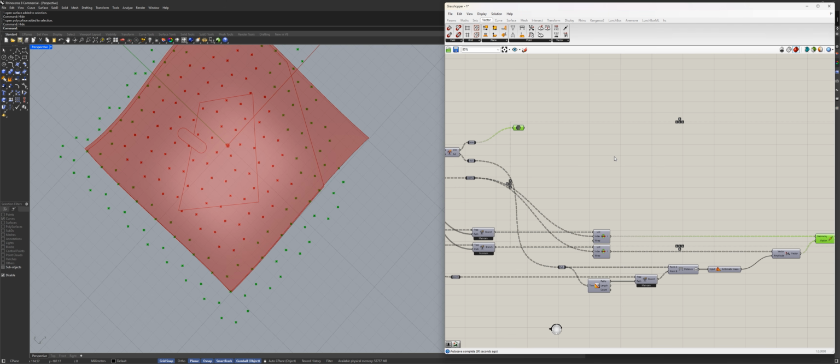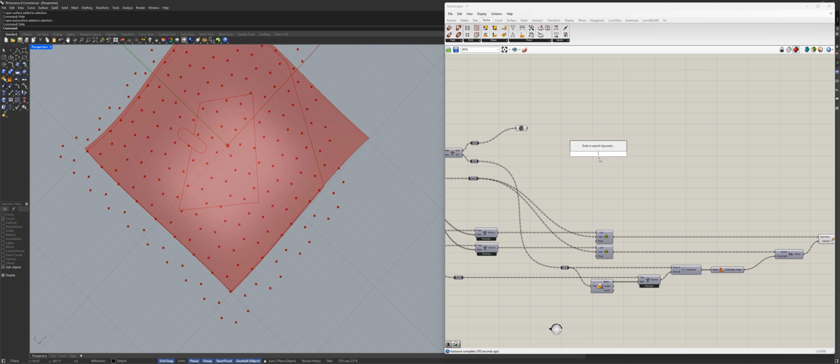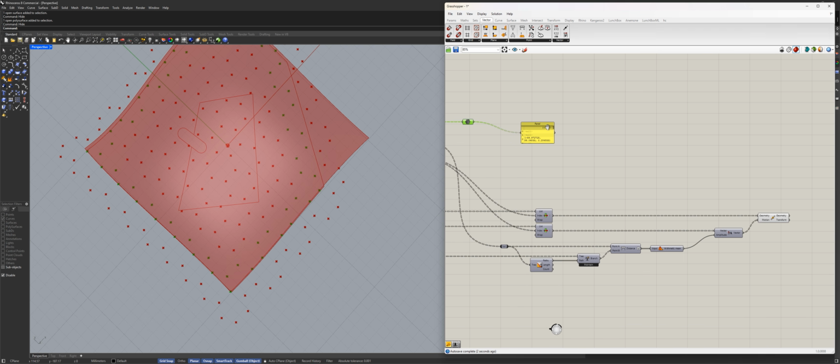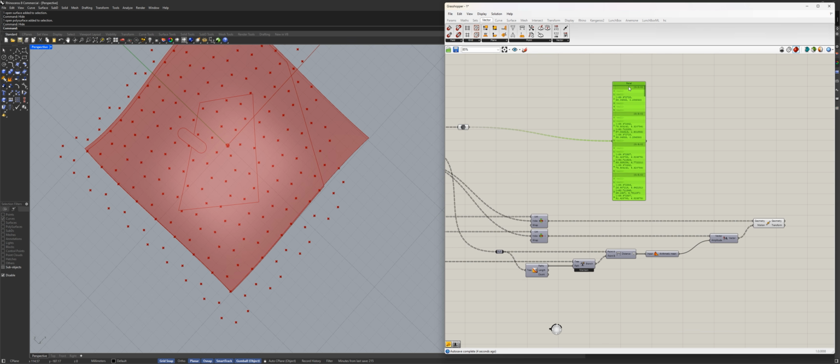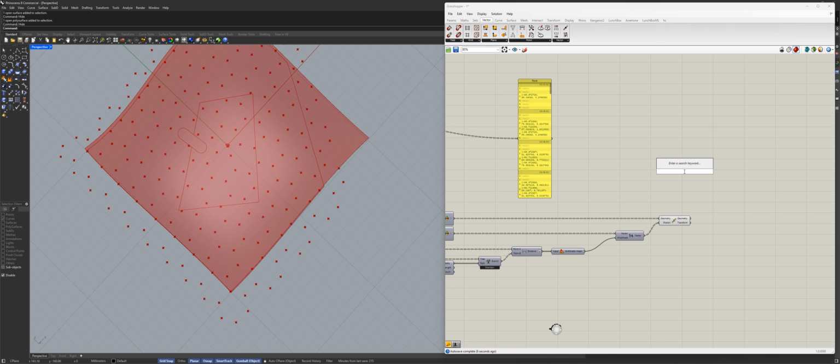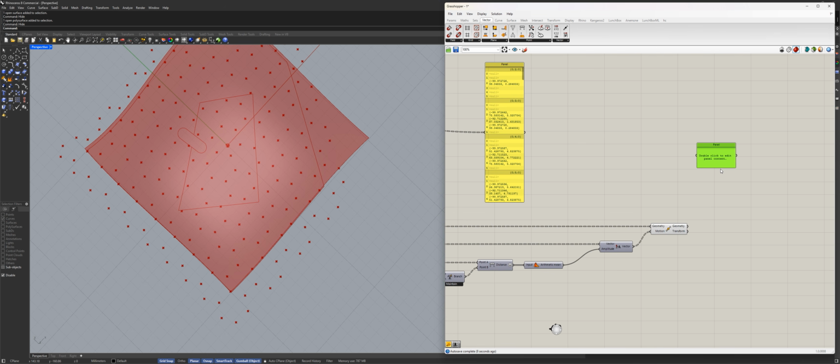So that's our new set, but it's separate, right? These values, our partial elements which are projected, are separate. In this branch, it still has nulls, remind you, and this one is the original ones which were projected separately here. We need to join them together. But if I use just a merge command, all the nulls will persist and I will lose the order of points.